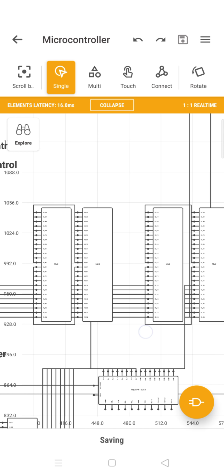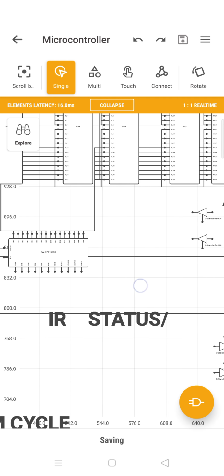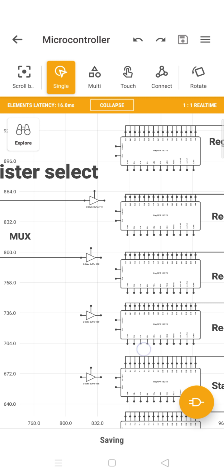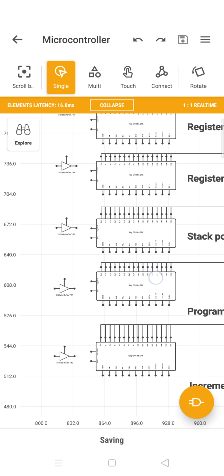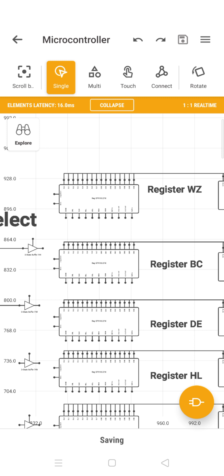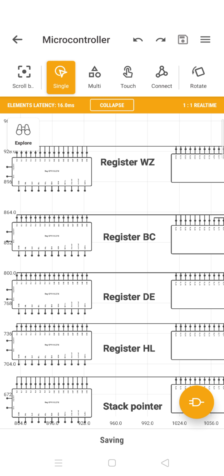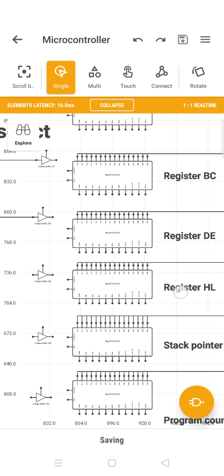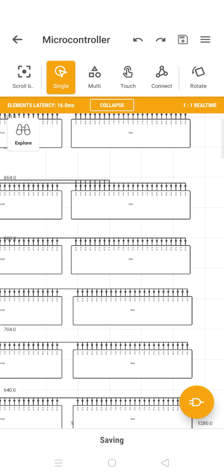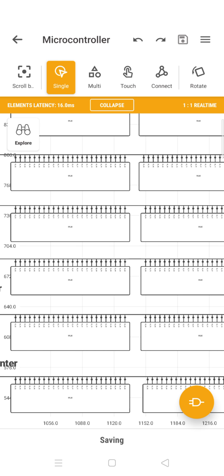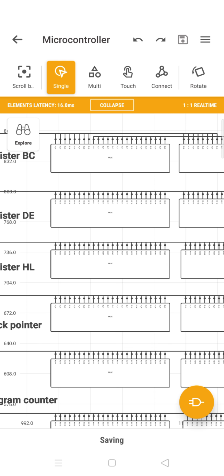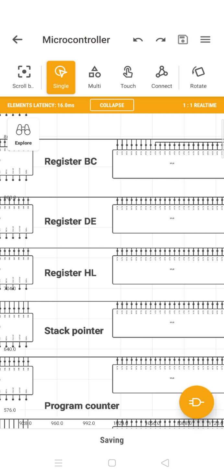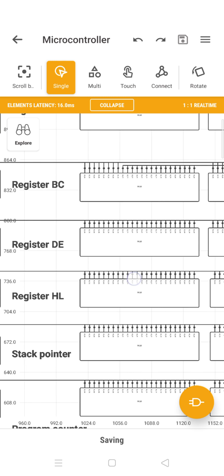Now this is a machine cycle generator, so I put in all the other registers right here. If you see all the other registers, 1, 2, 3, 4, 5, 6, 7. Okay, we have about 7 registers, all 16 bit, and each one is separated as WZ, register BC, register D. And this is the mux, for all the 16, 16, 32. Mux is needed basically for internal bus transfer. If you want to do any kind of internal transfer or external transfer, you use a mux.